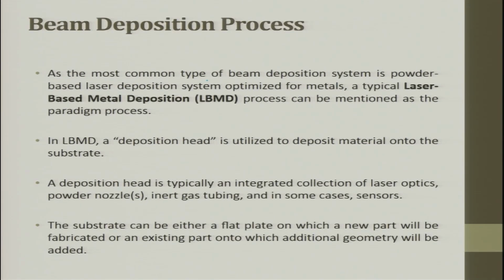As the most common type of beam deposition system is the powder based laser deposition system optimized for metal, a typical laser based melt deposition, LBMD, process can be mentioned as the paradigm process. In LBMD, a deposition head is utilized to deposit material onto the substrate.